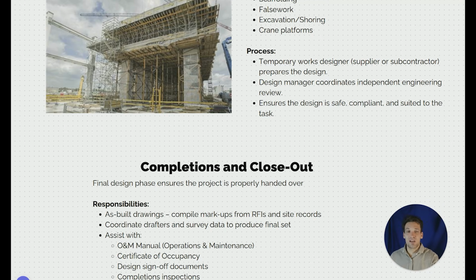So examples of the type of responsibilities would be developing the as-built drawings, compiling the markups from RFIs and site records, sending these to the drafters as well as any other inputs like survey data, so that the drafting or the engineering consultant can produce the final as-built drawing set. This is the set of drawings that the maintenance team will use to maintain the asset, that show where everything's installed, what was actually built at the end.